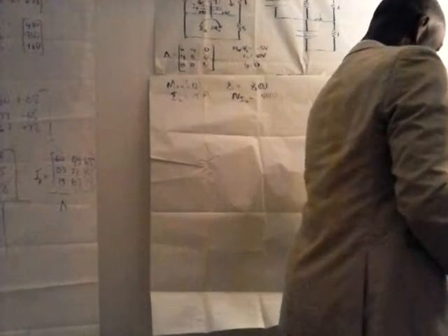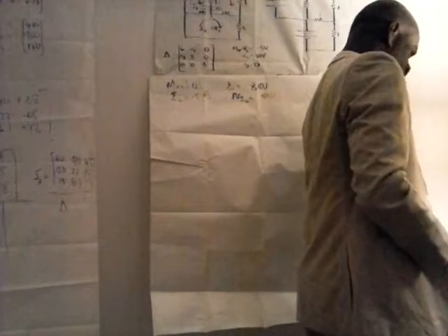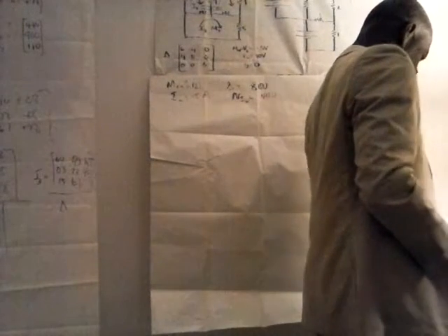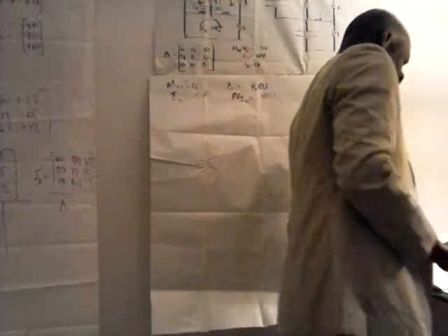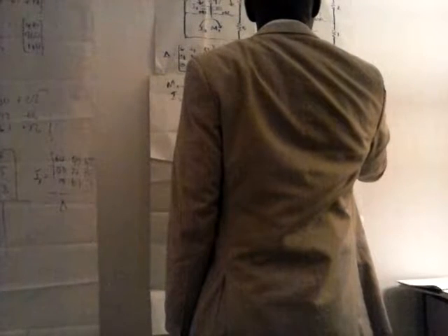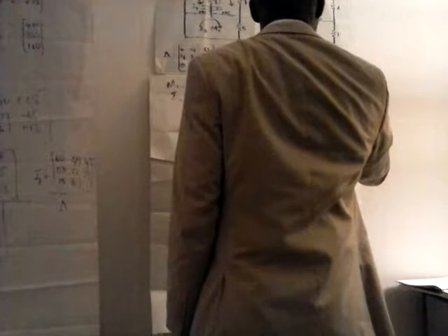We check here: delta equals 800 and Ni2 equals 400. So that I2 was then equal to Ni2 over delta, equals 400 over 800, equals 0.5 amps.